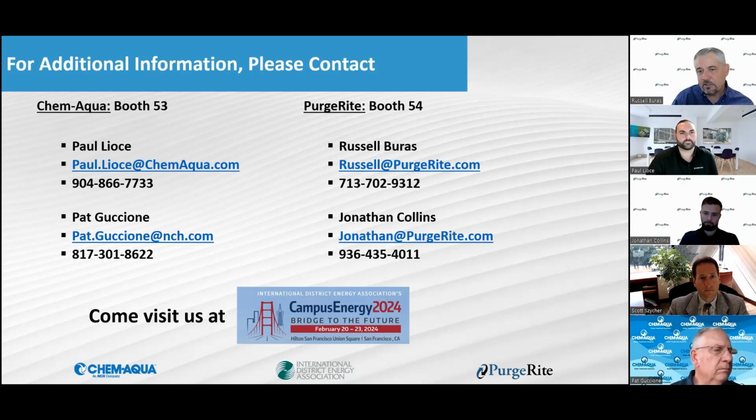You also are seeing a lot of chilled water underground pipe and other piping that will switch over from carbon steel to HDPE. So on the HDPE side, if you're only doing HDPE, we will typically do a clear water flush. For geothermal systems, you're trying to remove debris, and then you've got to be super sure you get all the air out of the downhole loops, because air can get entrained and entrapped in them, and you can literally lock them up. So you have to remove the air at least 2 feet per second velocity, and there's a lot of things with the geo side.